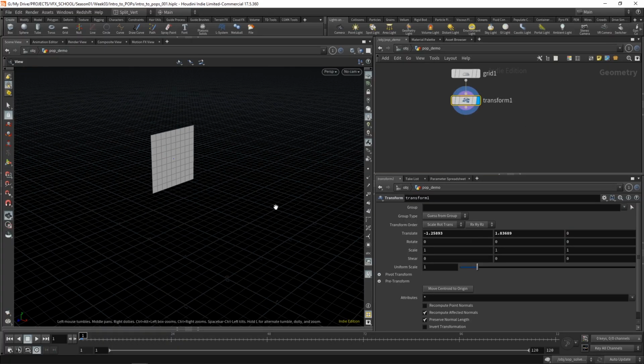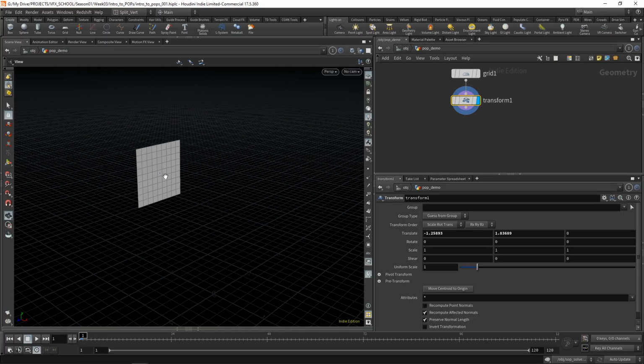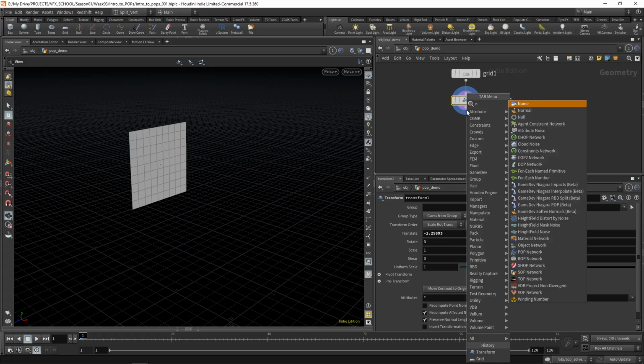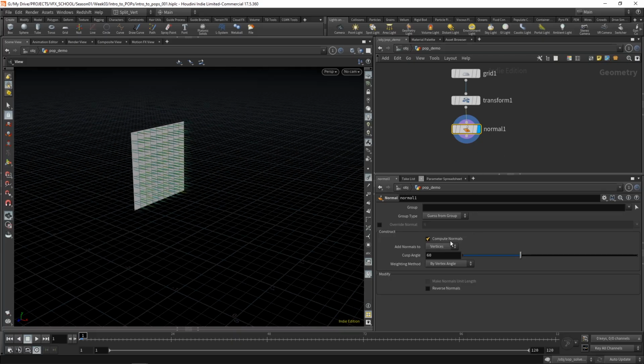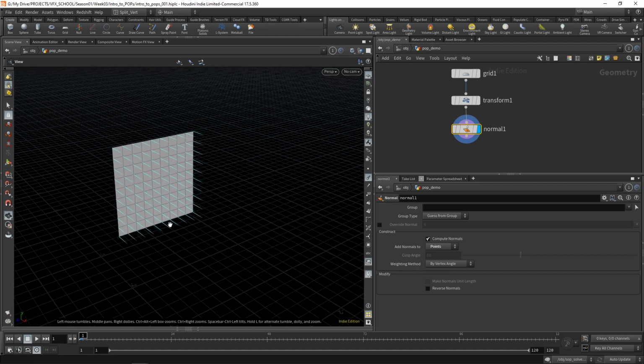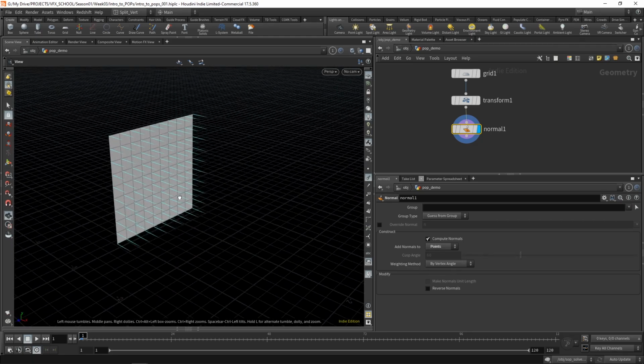One thing that you can keep in mind, and it's a very common workflow, is to take advantage of the fact that when you're generating particles from a surface, the particles have the ability to inherit the point attributes from that surface. So it's pretty common for us to, for instance, apply normals to this. Apply normals, let's make it visible. So now we have normals. Remember, it has to be on a point attribute in order to be passed through to the particles. So we have these normals.